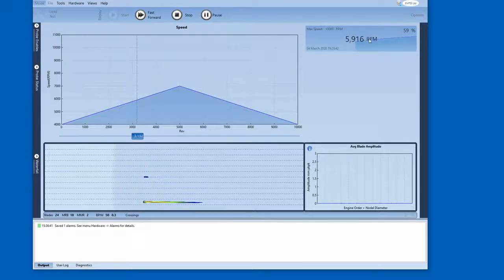So if you stare at the speed and watch down here, at 6,000 RPM, we've got a warning. Okay, speed has a warning level of 6,000. Now, there's only room for one alarm down here, and so that depends on its priority. I'll cover that in a minute. If I move that up to 6,500, we've got a full-blown alarm. So we've got two types: a warning and an alarm, and there's lots of parameters that you can define.